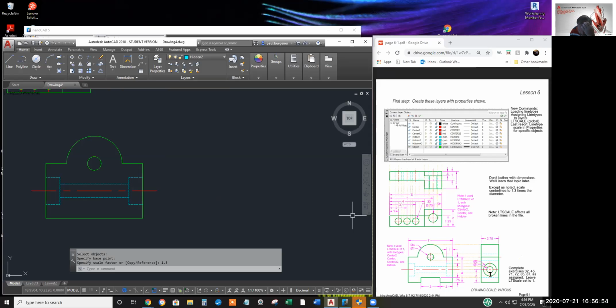I believe center line is next important. And then hidden line is least important. So if this happened to coincide with an object line, a center line, and a hidden line, I don't believe the hidden line would be drawn at all.